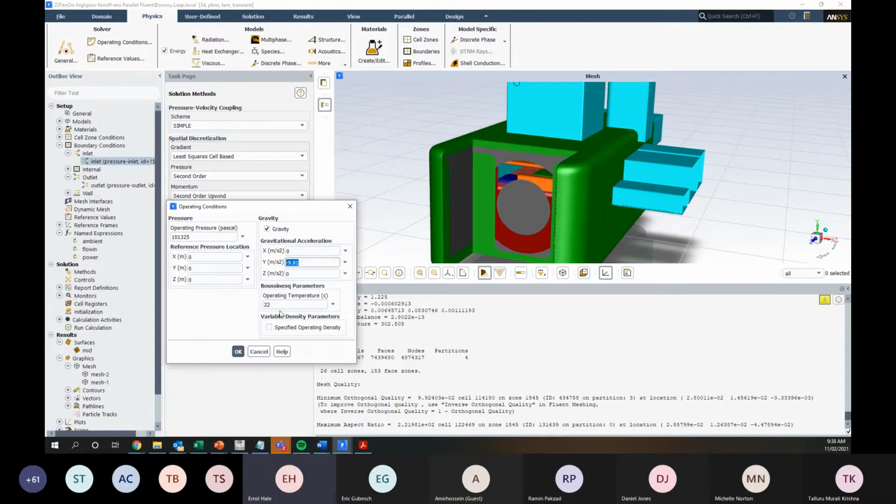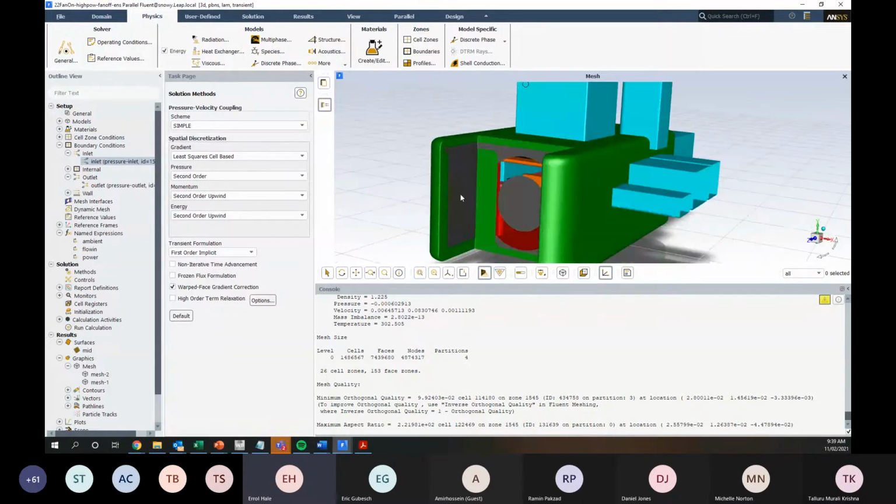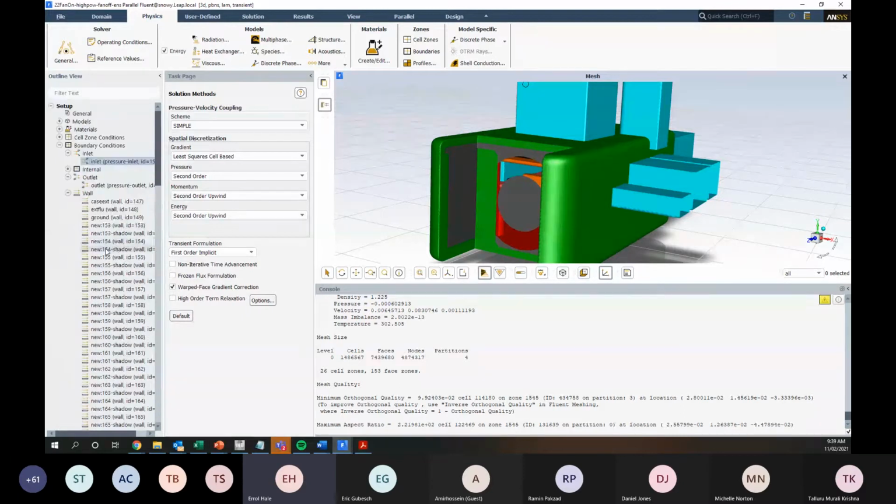So we just had our gravity turned on and our specified operating temperature. And then when our CPU would heat up, the fluid flow would flow away. So the inlet at the moment is 0, but we could have that inlet as a velocity and matching the fan. Our outlets are 0 pressure outlets, and our walls are all no slip except for these external walls.